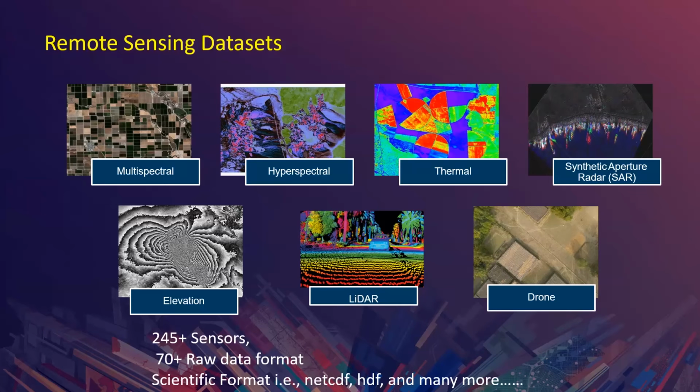Hyperspectral sensors measure energy in narrower and more numerous bands than multispectral sensors. Hyperspectral images can contain as many as 200 continuous spectral bands. The numerous narrow bands of hyperspectral sensors provide a continuous spectral measurement across the entire electromagnetic spectrum and therefore are more sensitive to subtle variations in reflected energy.